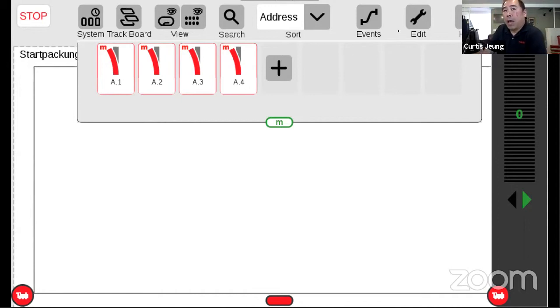So if you added another M83 or an M84 and it had the same address, or basically it doesn't even have to be the same address, because you can set the dip switches so that it has a different address. It's really your choice. And hopefully that wasn't too confusing in the long run for you. But the next device, if it's an M83, will actually have a B.1, B.2, B.3, B.4. And I'm referring to this annotation here. Okay. So it'll just be a B1 here. Excuse my writing. It's hard to write with a mouse. Okay. And so on and so forth.